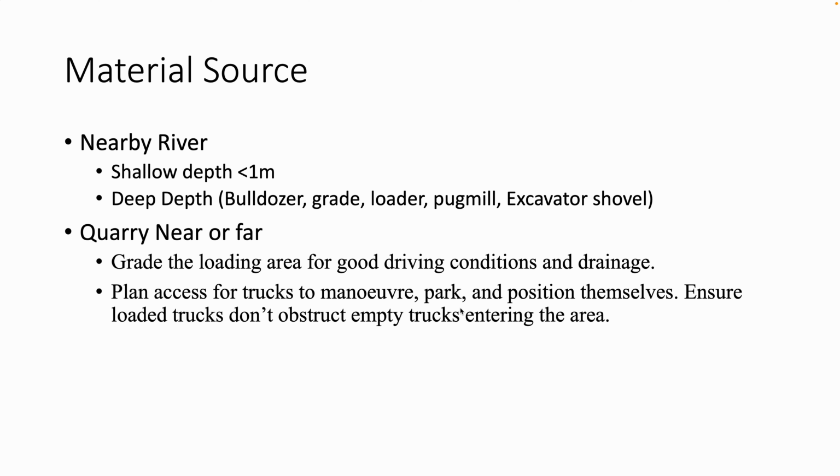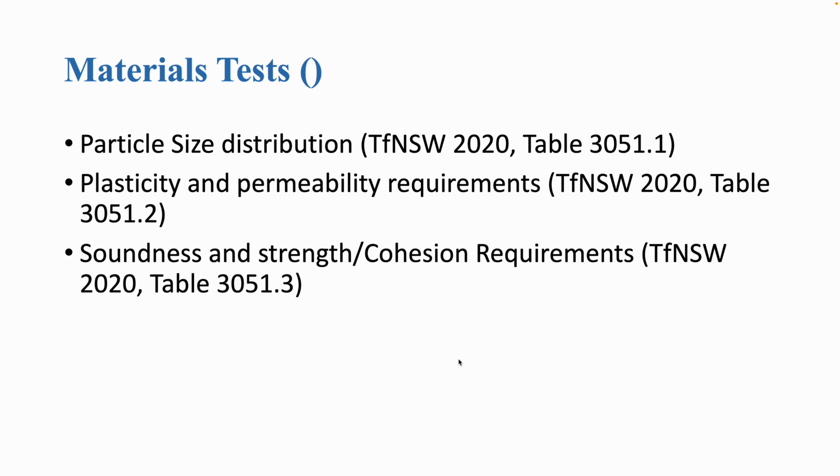And when it's a quarry, we have to beware and look for the maneuvering of the trucks, the parking and positioning, so that the trucks don't obstruct any other trucks entering the construction area. Some tests we need to do on the materials: particle size distribution, plasticity and permeability requirements, soundness and strength requirements. All are from Transport for NSW standard tests.